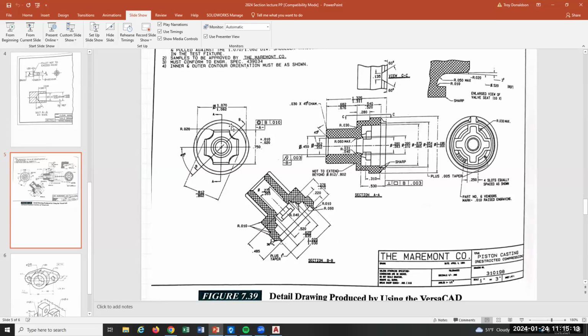If they would have put the hidden lines in this, see how they omitted all the hidden lines, just left them off? It would have been an absolute mess. It would have been solid hidden lines. That's not helping anyone, so just leave those out. If you're going to do a section, you're pulling out all of the internal geometry in the section. You don't need all those hidden lines in here. Just get them out of it. Okay, same with this. There's a couple hidden lines back here. Most of it's visible, I think, unless this stuff's in the way out here, right?